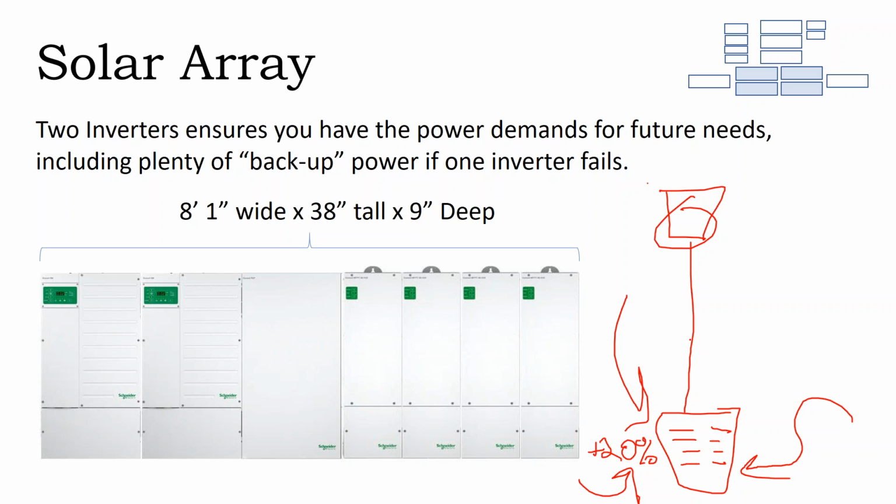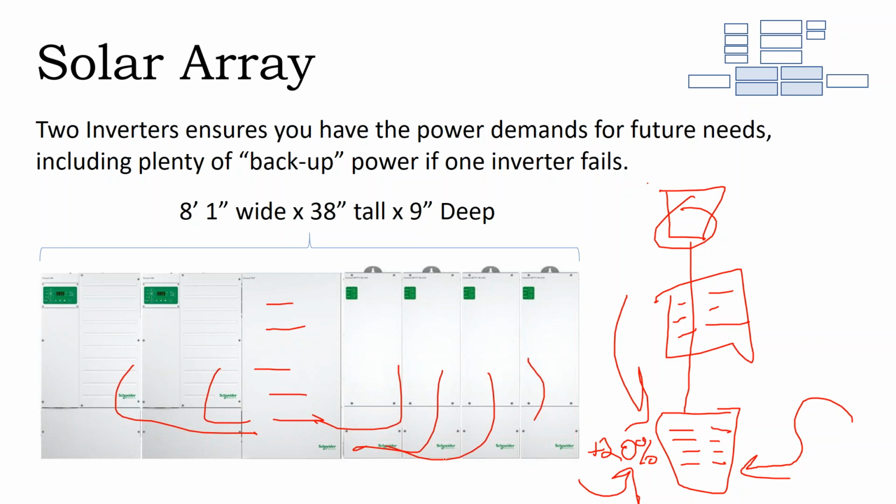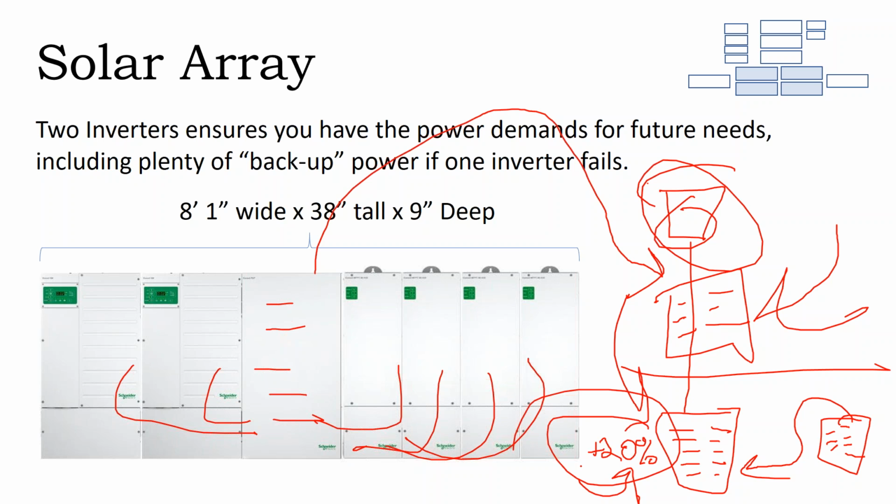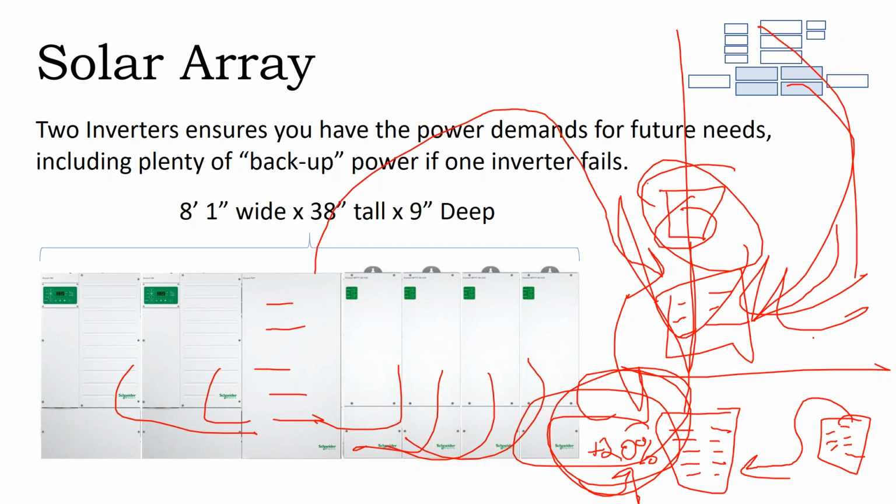And when you do a supply side connection, you put in a dedicated panel that's just for on-site energy management. So this is your dedicated panel for your energy systems, and that might have a transfer switch in it. This panel can be landed between your utility connection and the whole house. A solar array on a load side connection may only be able to power a critical load panel that's kind of off the main, whereas a line side connection can supply the whole house. And instead of just using an additional 20% at the bottom of the bus bar, a supply side connection, it doesn't matter if it comes from the utility or from the solar array, can supply 100%.